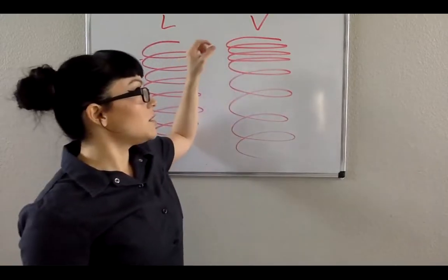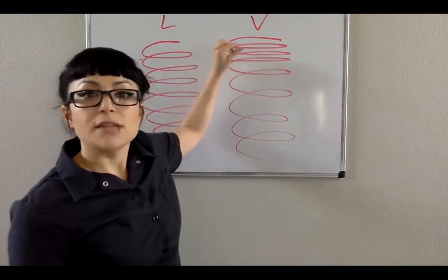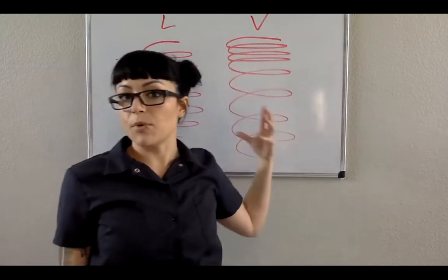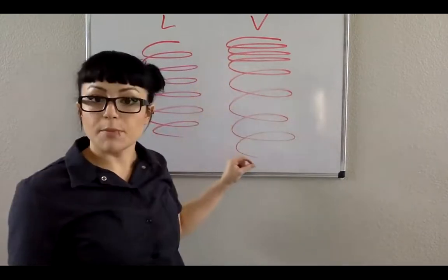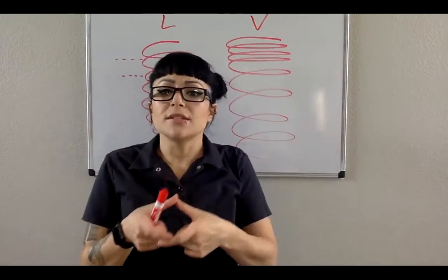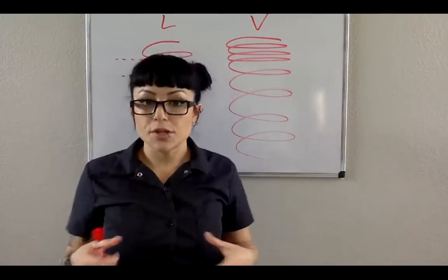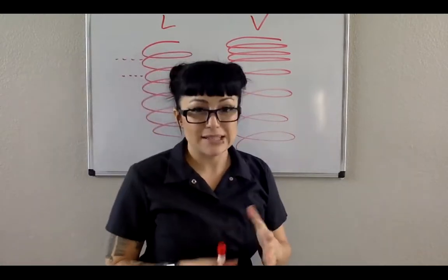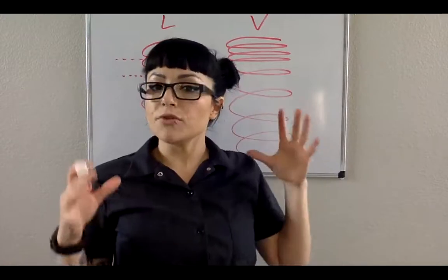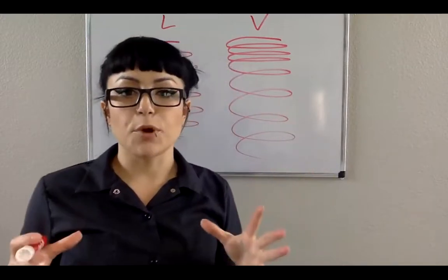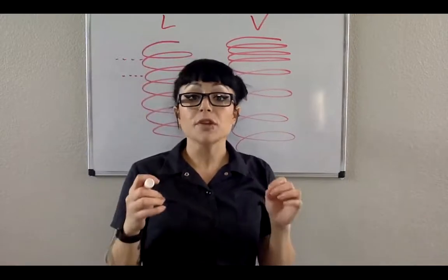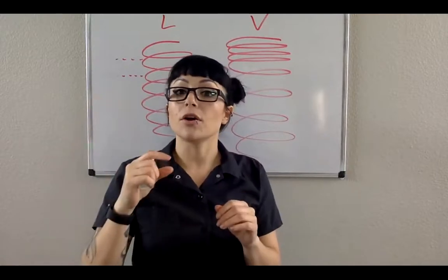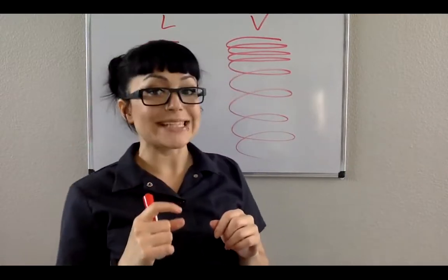The distance between our coils tends to be a way that people change the spring rate from top to bottom on a variable rate. Sometimes they will change the diameter, smaller and larger, to change the spring rate on coils. Those are two really common ways to get a variable rate spring. But the most important thing to know about variable rate springs is that most of the time, the more weight you add, the harder or stiffer the spring rate is going to get.